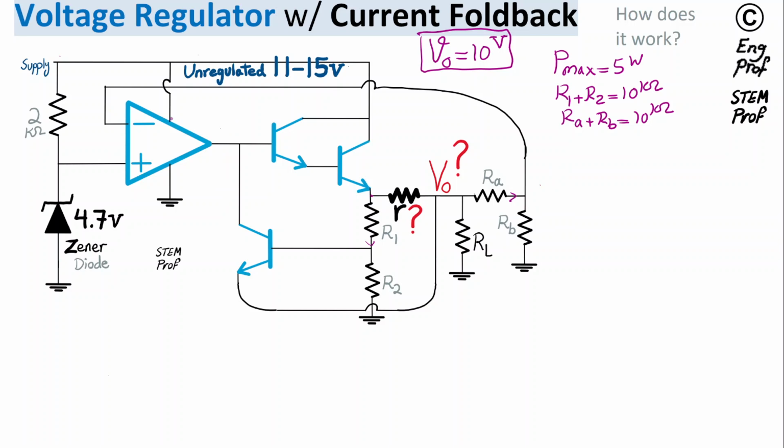Okay, so with that, meaning proper bias of the op-amp and also negative feedback, we can make the assumption that the op-amp is operating in the linear region, and as a result I can say the op-amp is not saturated. That means the virtual short is valid for the op-amp, which means the voltage at the positive input terminal is equal to the voltage at the negative input terminal.